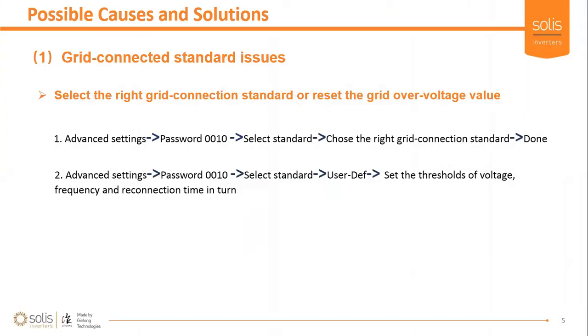Here we can see the standard issues and their solutions. First of all, on the inverter display, we should check for the right grid connection standard and reset the grid over voltage value. On our inverter, we have some settings which help to choose the right grid connection standard.